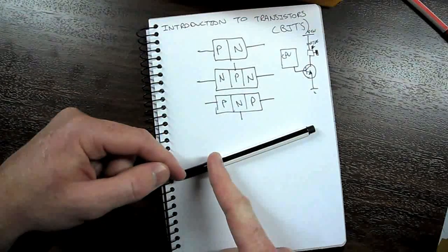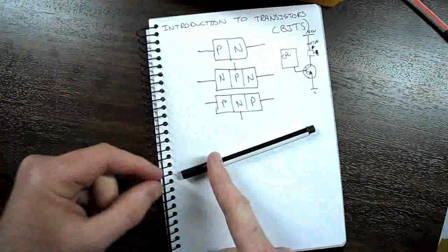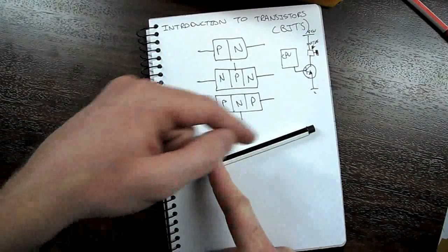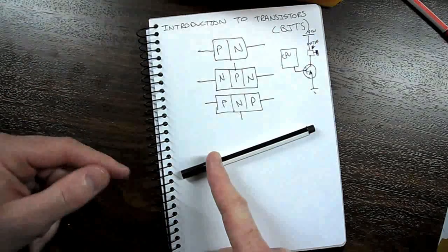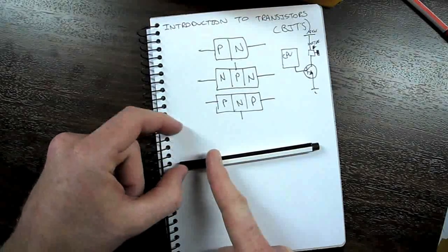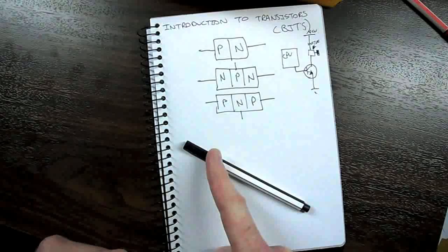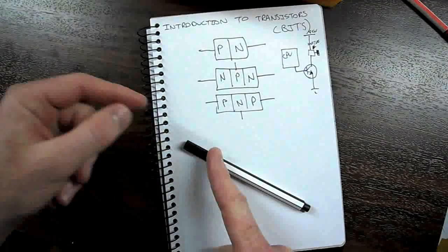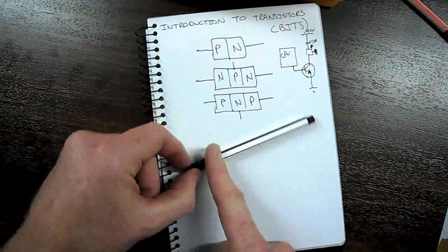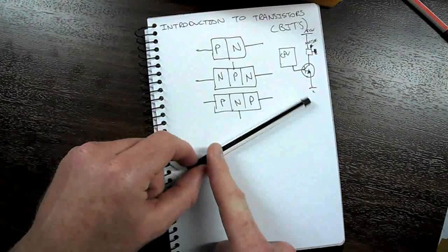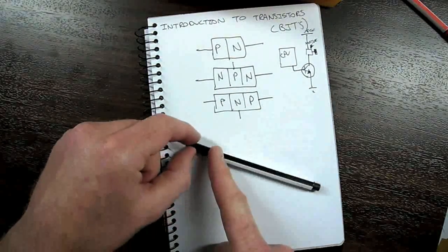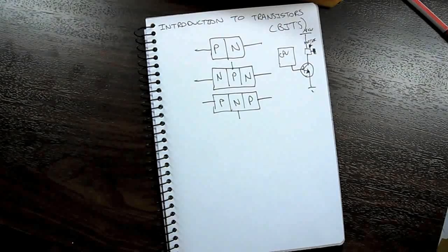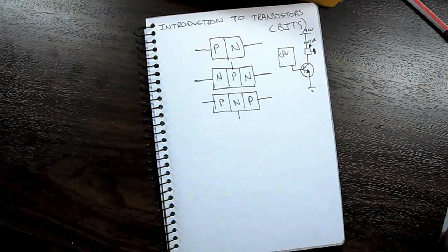The input has moved by just a few millimeters, but what has the output done? The output has moved quite a bit further than what the input did. So if I move this a millimeter, this might move by a centimeter. So it's actually amplified my input. If I move it the other way, let's move it by a centimeter or so, you can see the output has moved a much greater distance than what the input did. So as we get a signal coming in on the input that goes positive and negative, just by a little bit, you can see the output swings a lot more than what the input does. So a transistor is just like this. We have a small input, it will then amplify that to give us a big output, which is a representation of that input.